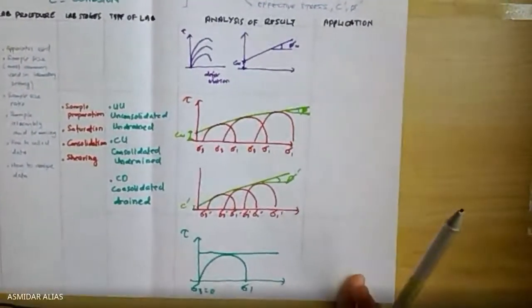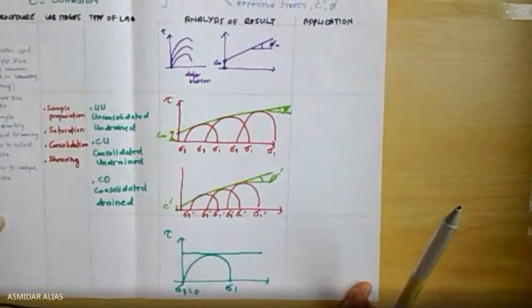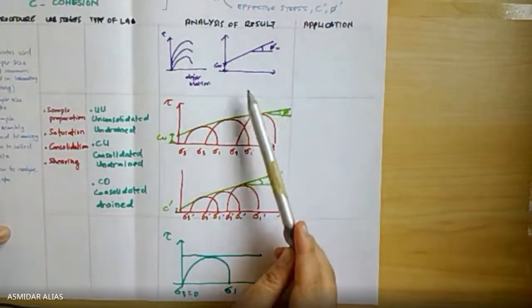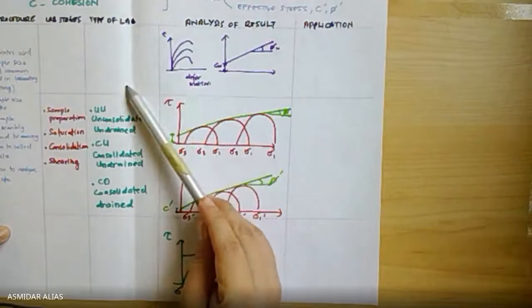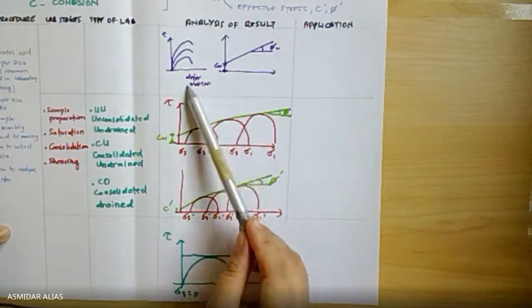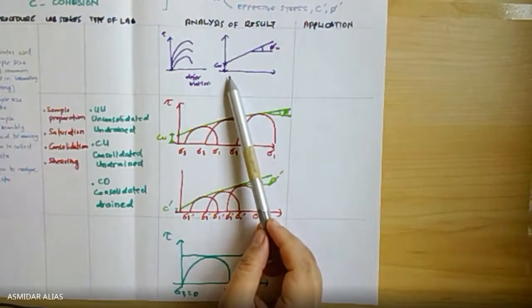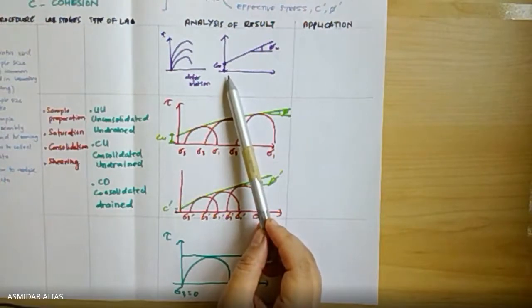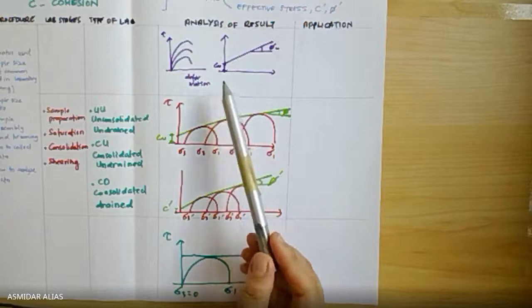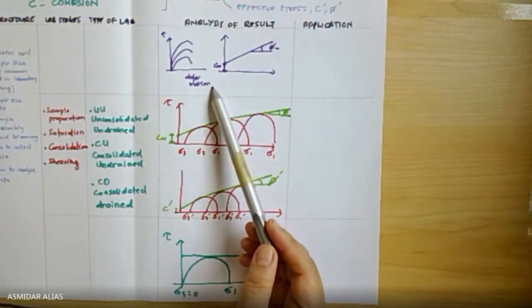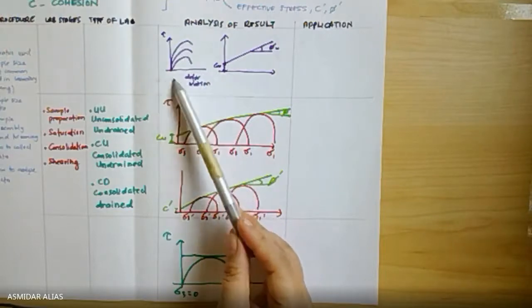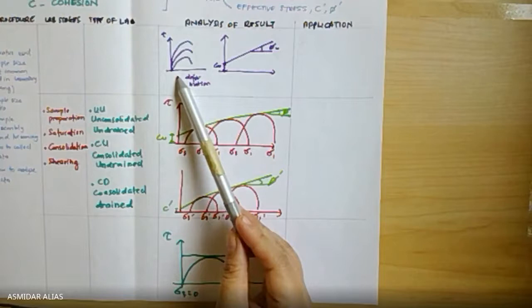Okay, and then the second last part is the summary of this chapter. You can get from lab data, you can have your own analysis here, because we know our objective is to find the shear strength parameter. The objective is very clear. So towards the end, when you analyze the data, make sure you get whatever objective that you already intended. So for the shear box test, you are doing the deformation, you are doing the shearing test, and then we will calculate the deformation at the same time.